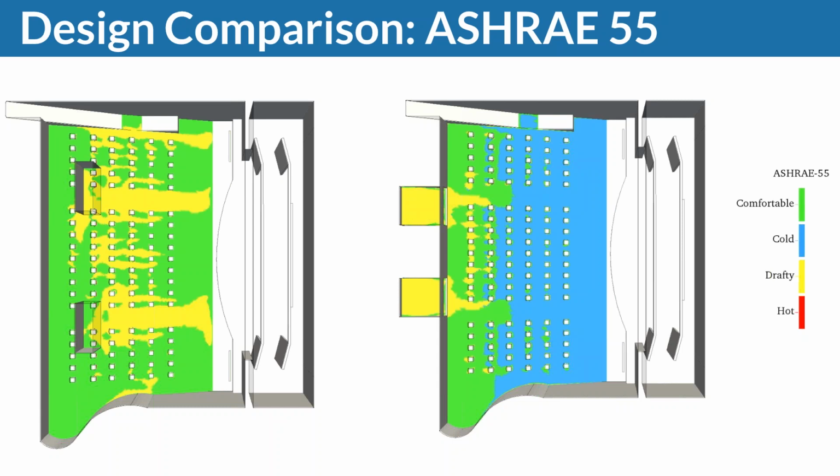One registrant asks, what type of model can be used with SimScale, or what kind of CAD software is compatible with it? Fundamentally, how we started is with general exchange formats, such as IGES, STEP, or even STLs you can bring in. And over time, we've added more and more commercial formats. So nowadays, for example, you can also bring in SolidWorks models or Inventor models, depending on the CAD software. And we're in fact working right now on compatibility with other AEC CAD systems such as AutoCAD or also Revit. And that will be released shortly. But as of now, most CAD systems support one of the general exchange formats, such as STEP or IGES, and that works fine most of the time. So that should work.